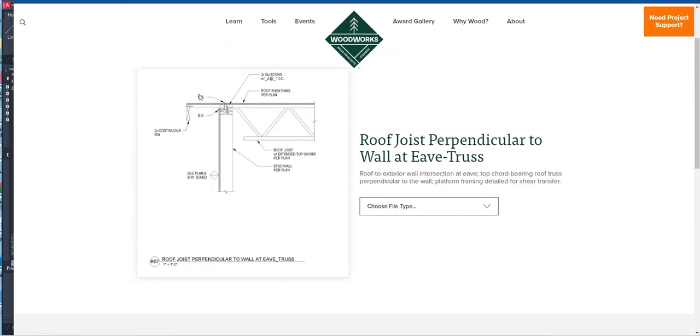and it will show you a preview of that detail, and then you can actually choose a type. This one comes with a Revit detail, an AutoCAD detail, and a PDF. Some details, there's no drawing or Revit, it is just PDF. And if that's the case, then you don't have any choice, but you want to use this. So you might have just to draw this out, or you can actually use a PDF file for this one. Okay, so let's try to download a PDF.